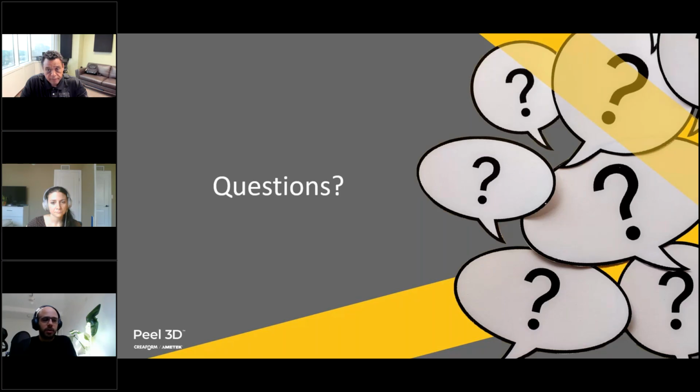Sure. So actually, when working with ExactFlat, we don't really need an extremely high resolution for just scanning the geometry. The reason being is that we don't really want to overload the software with way too many vertices. So depending on the size of the object, we'll basically choose our resolution settings based on that. So let's say that if you're flattening something the size of a helmet or just something that has a very small surface area, in that case, you may want to use a resolution of around 1 millimeter.